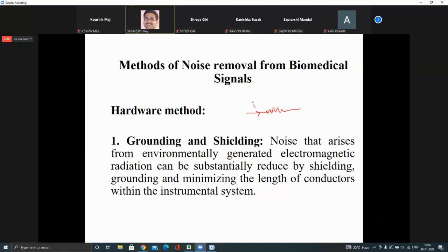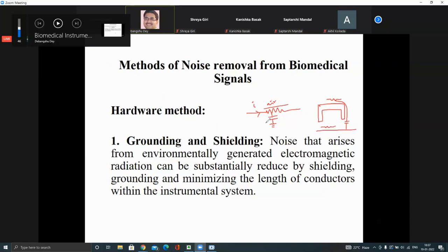It can be a metal film, thin film resistor, okay? So above that metal or conductor there will be some insulation coating. Even if it is a bare conductor, then also air will be there. So whenever you are using a metal in contact with air, with some ground, some capacitor will be formed. That capacitor you cannot see, you cannot measure exactly, because at different positions, say you are placing it over a table, maybe the ground is far away, so the stray capacitance will be something else than if you are placing that close to ground. So at different positions, this stray capacitance will be different.